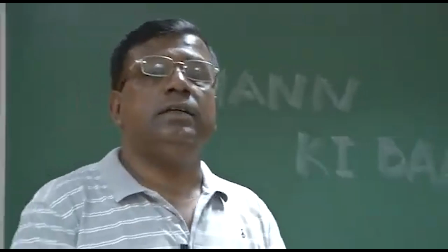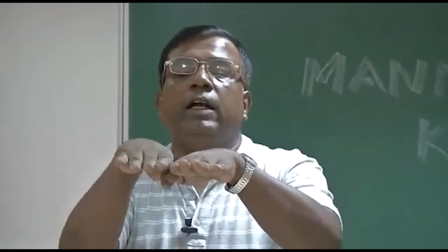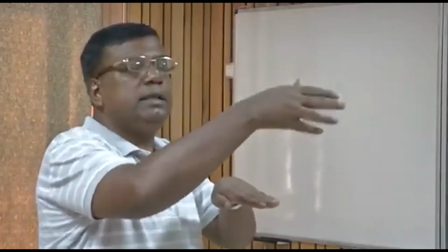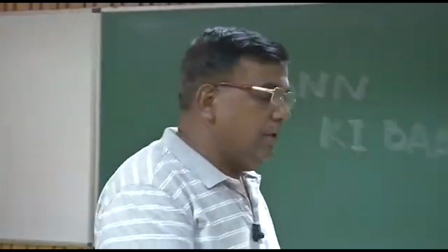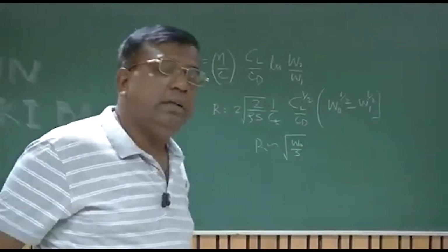One of the most important things I need to mention here, please understand: whatever power required, thrust required, range, endurance we have discussed, we have discussed in a standard atmosphere. That is, we have not assumed any wind blowing. Suppose the aircraft is going like this; in actual atmosphere there could be wind following the aircraft, or wind from just the opposite direction of the motion of the airplane. So if the airplane is going like this and the atmospheric wind is coming like this, then we say it's a headwind. The aircraft is experiencing headwind.